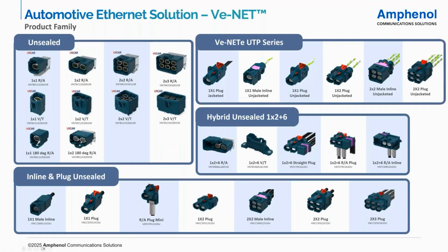What did we develop for VNet? VNet we developed for the unsealed board connectors: right-angled, vertical, and I want to draw your attention also to the right-angled ones with a reversed interface, which looks at first instance a bit strange. But the reason for this is actually to have a lower height of the total application.